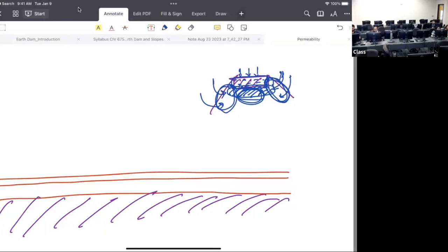The way people try to do it, not only one way, there are several ways. One is you cut, you replace it with good fill materials, and then build on top of it. That's one way. The second way is you have the existing soil, and you try to change the characteristics of the soil by adding some lime in. Now, what does the lime do?